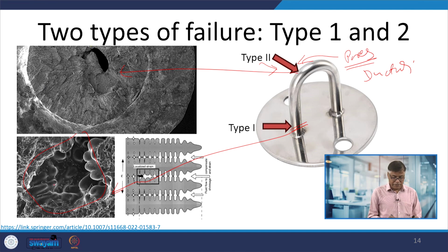If you see the morphology of these pores, these are shrinkage pores, as evident from the presence of the defect, and large air pockets were also observed in the bent section. So, the presence of the pores was the main reason behind the failure of the U clamp.